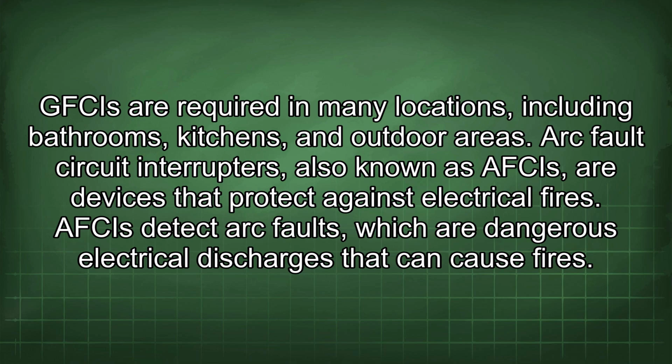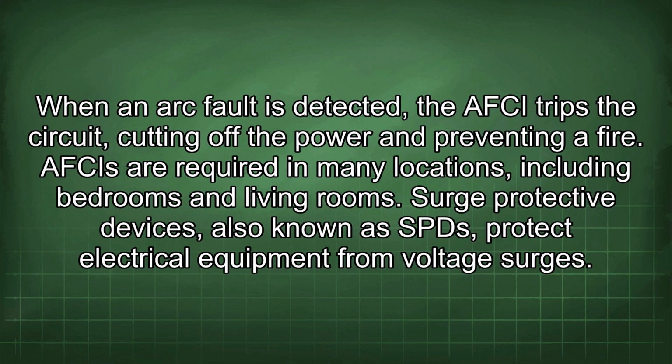Arc fault circuit interrupters, also known as AFCIs, are devices that protect against electrical fires. AFCIs detect arc faults, which are dangerous electrical discharges that can cause fires. When an arc fault is detected, the AFCI trips the circuit, cutting off the power and preventing a fire. AFCIs are required in many locations, including bedrooms and living rooms.